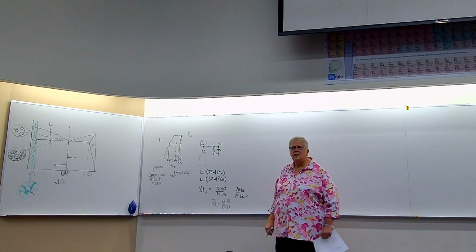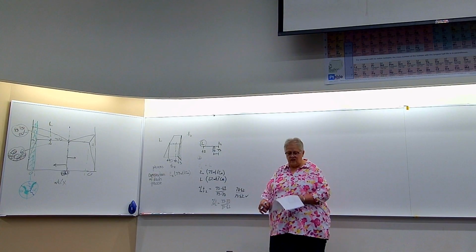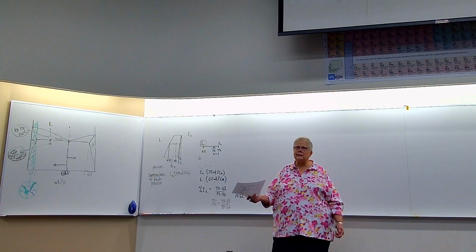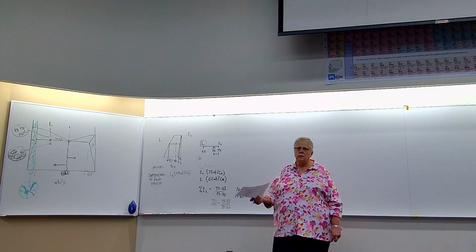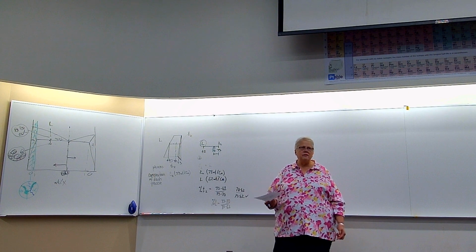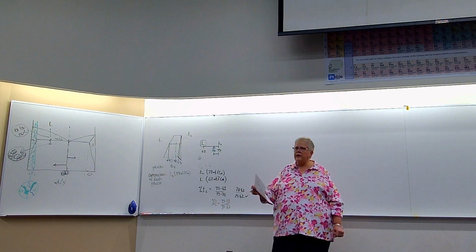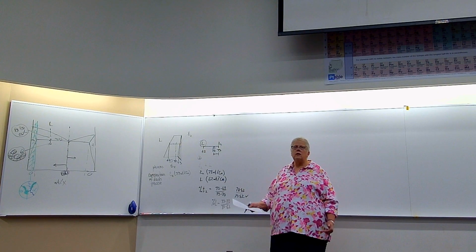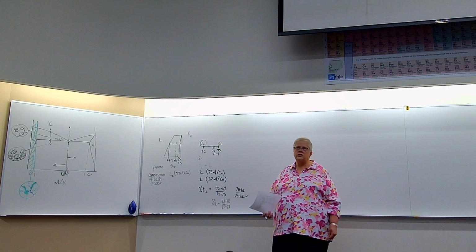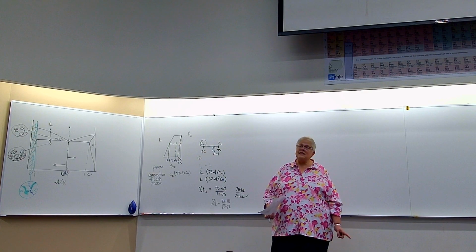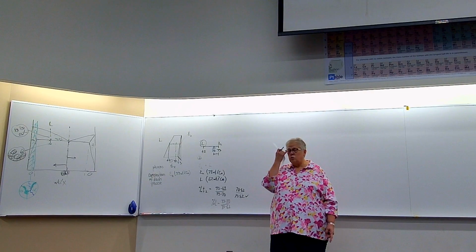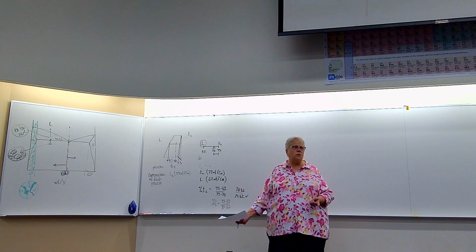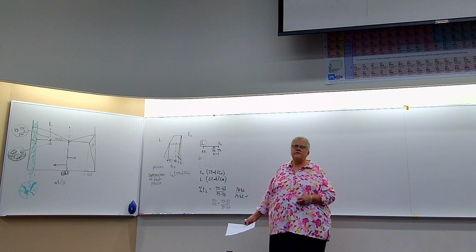Now, even though this is an incredibly complicated phase diagram, the method that we use is the same. If I put a point on there and I put a letter X next to it and I said, look at point X and tell me what are the phases, what are their compositions, what are the relative amounts, that point will either be in a single phase region, where the composition of the phase is the composition overall, and it's 100% of that phase.